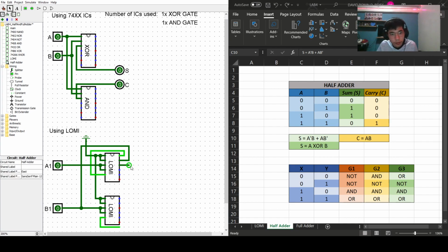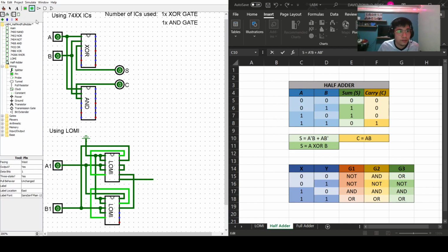So we could just simply put it to this one, OR, and then we need another AND gate, which is for our A and B prime. So let's just do that. A, so let me just delete this, edit it. A and then B prime, and we get that. So we need that result to be ORed, and using the OR gate here, we actually get our output sum.